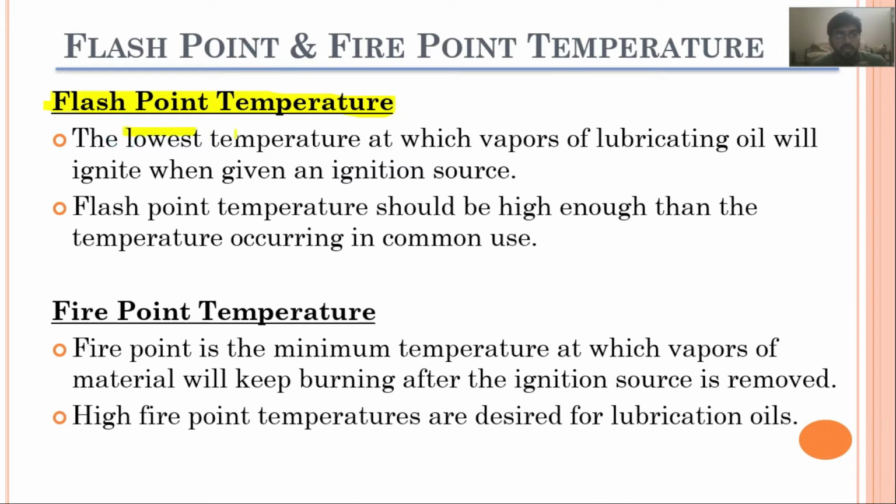So the flash point is the lowest temperature at which vapors of lubricating oil will ignite when they are exposed to the ignition source. And flash point temperature should be high, high enough than the temperatures which are occurring during the common operation.